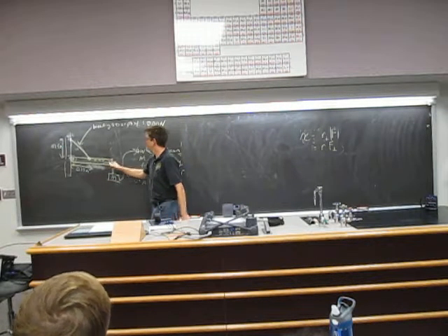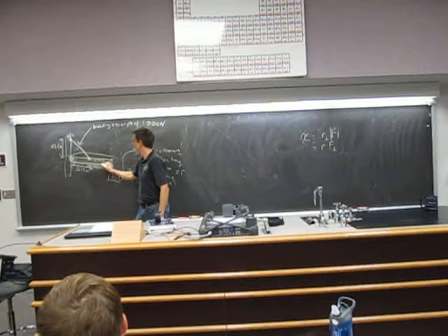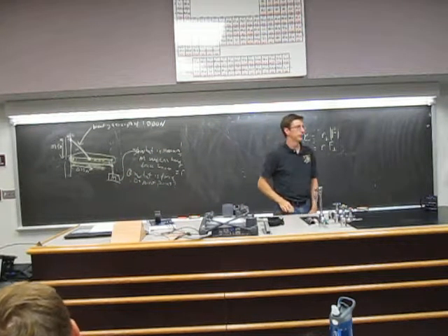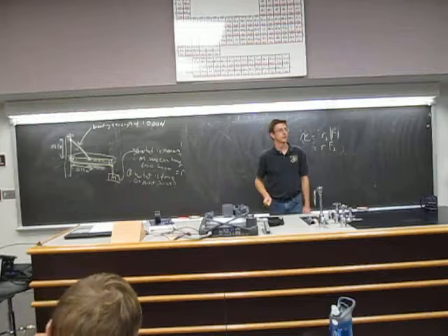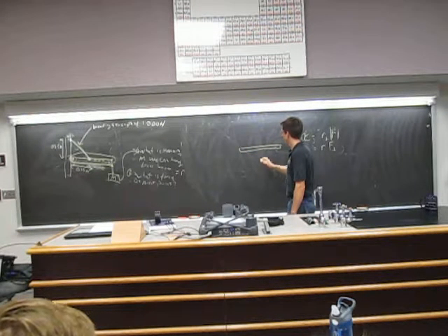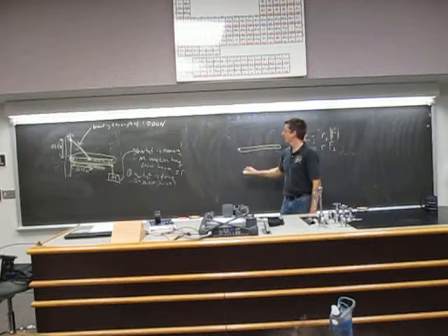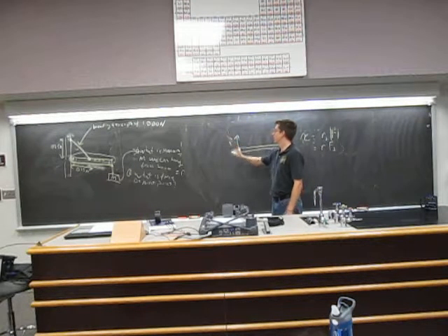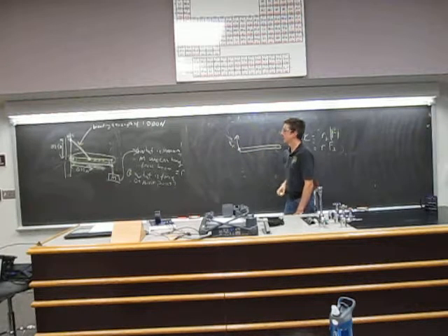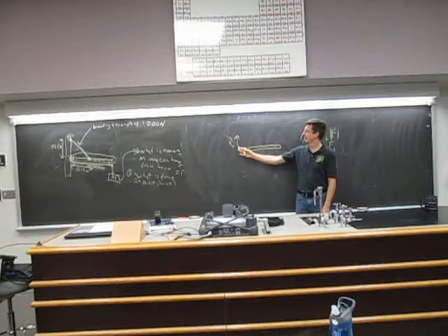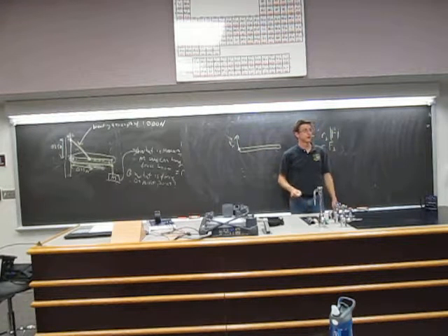Okay, so I'm going to start out with 45 degrees. For these types of problems, you just draw the forces on the boom more or less where they're at. So it's like a free body diagram. I have some sort of force at the hinge, I'm just going to draw it this way. I don't know exactly which way it goes right now, but we can solve for it later.